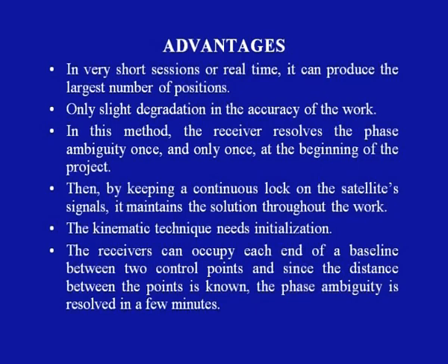The kinematic technique requires initialization, that is, the receivers occupy each end of the baseline between the two control points, and since the distance between the points is known, the phase ambiguity is resolved in a few minutes' time.